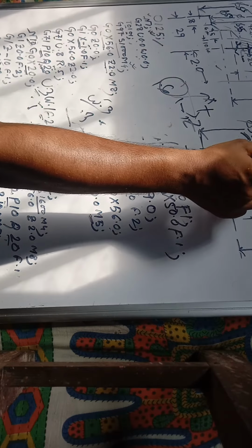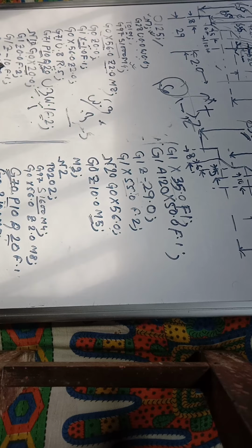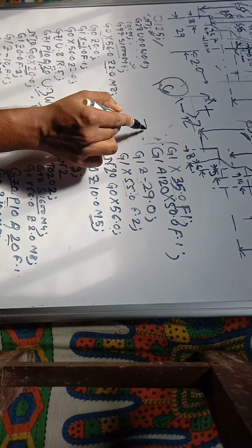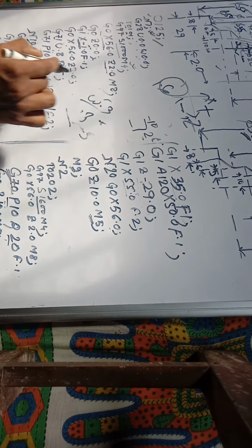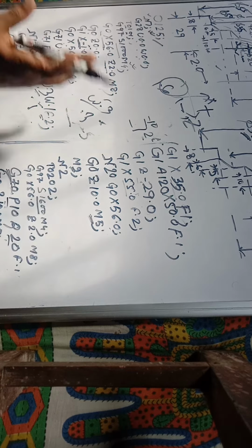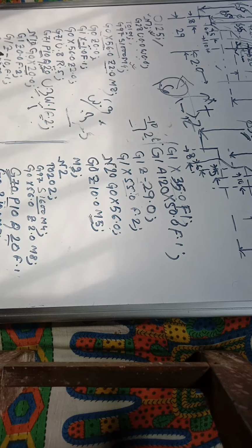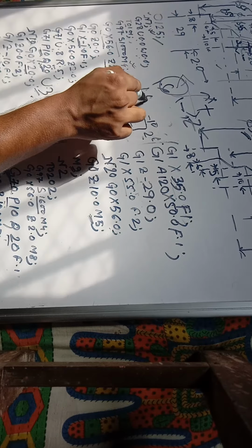After that we have to turn it by means of 10 millimeter. So I have given 10. After 20 millimeter, it will turn simply 10 mm, because it is moved to the negative side of the Z. So I have given the negative value. After that it will cut it angularly by means of a 45-degree angle.